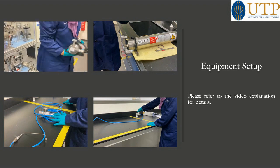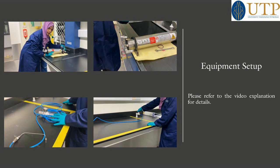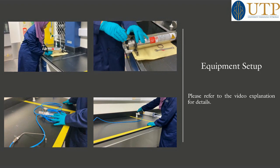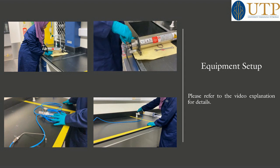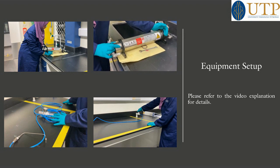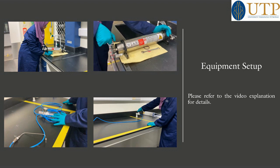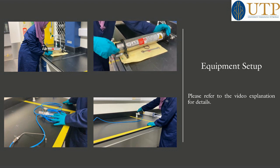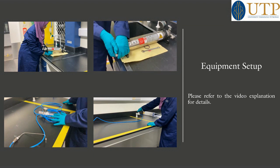So now, if we want to open this one, our first work is to open this thing. Why are we opening this one? If this one is closed, that means inside my accumulator it's air packed. That means fluid and air. So it's very packed. So when I open this one, some fluid can come and some air can pass through this line. Now we will open.